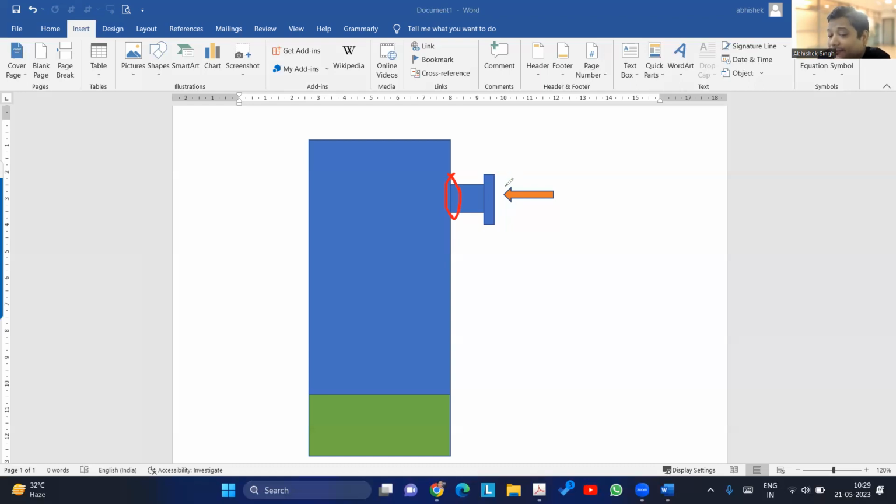Now let us say this load is given to me. We have all 3 loads. I've indicated only one, but you can consider there are loads in all the 3 directions: circumferential, longitudinal, and radial. All the loads and moments, the 6 loads which we typically see, are all there. But that is given at the flange face. The loads are given at the flange face. Now, can I use that load as it is for WRC?